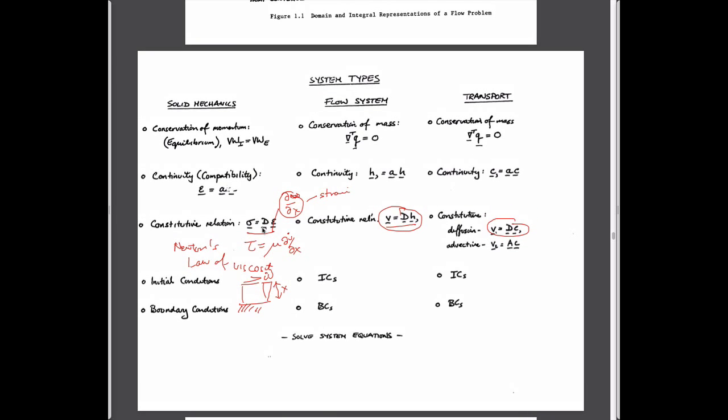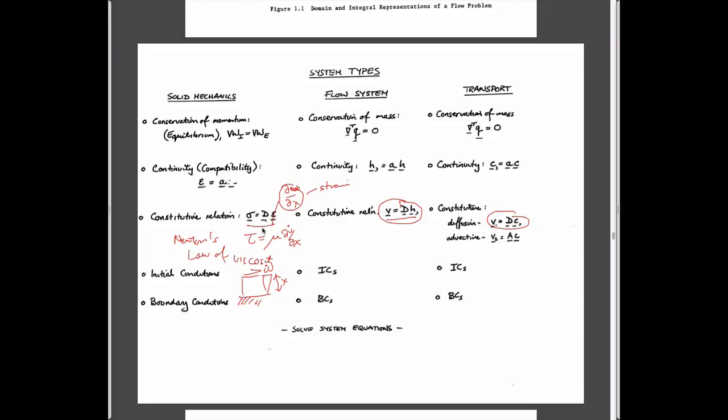So the dynamic part of porous media flows is not the fact that we deal with inertia, like in a building that's flapping backwards and forwards. It's the inertia of the building that controls the period at which that goes compared to the excitation on the base. But the control typically in these pseudo-dynamic systems for deformation is that fluid pressures change with time. Those are the rate-limiting components.